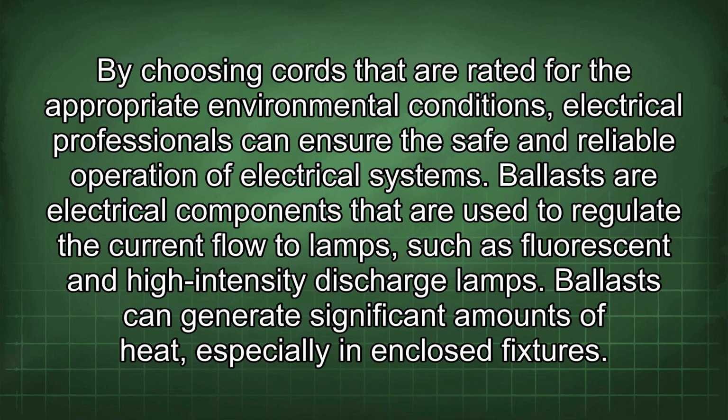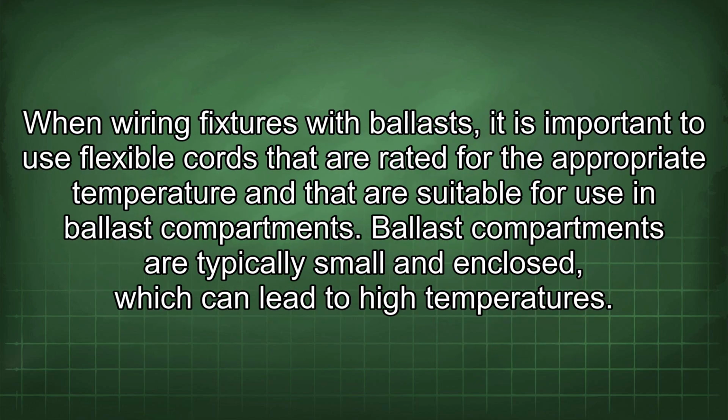Ballasts are electrical components that are used to regulate the current flow to lamps, such as fluorescent and high-intensity discharge lamps. Ballasts can generate significant amounts of heat, especially in enclosed fixtures. When wiring fixtures with ballasts, it is important to use flexible cords that are rated for the appropriate temperature and that are suitable for use in ballast compartments.